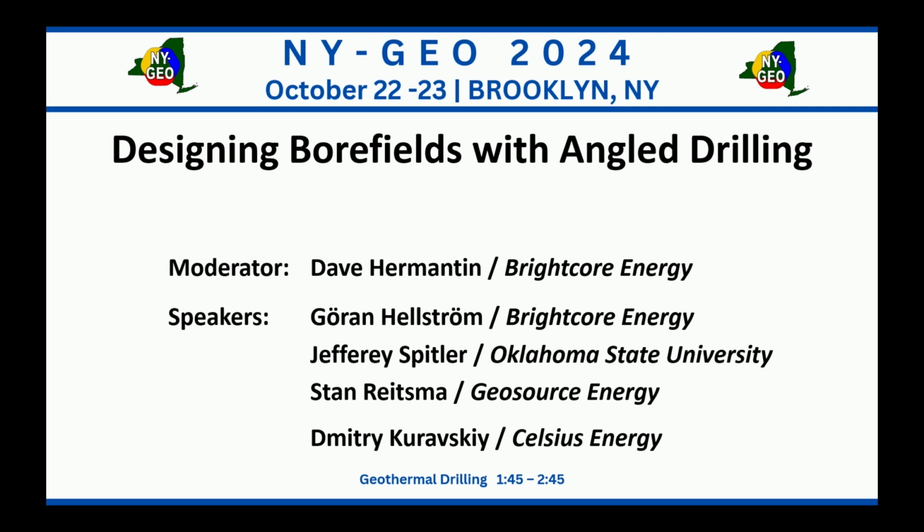But what Stan mentioned initially, and I was basically piggybacking on, is more about the soft bedrock. In the Northeast, for example, before you reach the hard rock, where you can seal your casing, if you're using high pressure air or high pressure fluid to circulate, this fluid under pressure breaks through to the nearby wells and basically pushes your grout out. So it's extremely critical when you develop inclined bores to create a proper seal at the bedrock to be able to maintain the integrity inside the well bore. Sometimes it's quite challenging, and adds to the cost aspect as well.